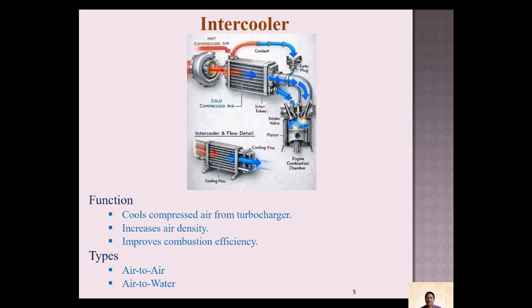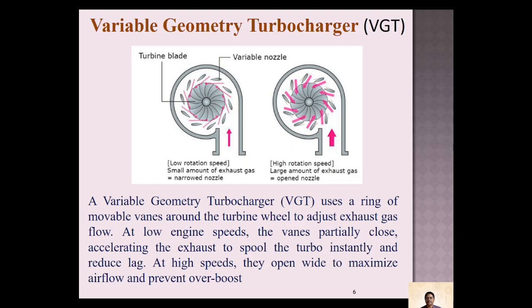There is an intercooler, which is required to cool the air from the turbocharger. It increases the air density and improves the combustion efficiency. Air-to-air types are there, and air-to-water types are there. You can use water also to intercool the compressed air from the turbine.